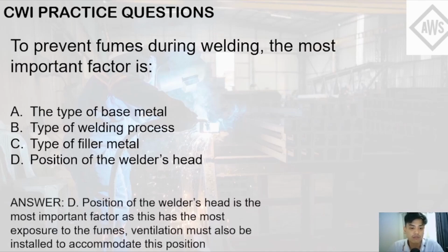It is the most important factor as this has the most exposure to the fumes, and not only the welder's helmet but also the ventilation, the type of ventilation used for that activity must also be designed to accommodate the position of the welder's head.